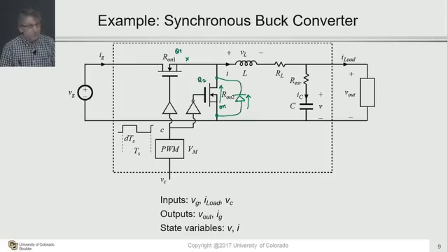And so this Q2 MOSFET has to be synchronized to the operation of the control MOSFET Q1, and in fact it has to be performing the rectification function in a synchronous manner, in a timed manner that corresponds to what the diode would be doing if the diode were present, which is why we have this term synchronous in the buck converter. Synchronous buck converter is a very, very common component. You probably have 10 of those in your pocket right now performing conversion from the battery down to various pieces of your smartphone. Okay? So it is a very, very commonly applied converter circuit.